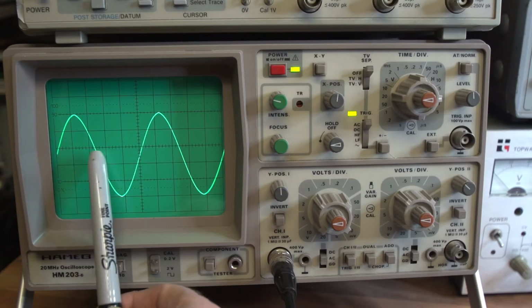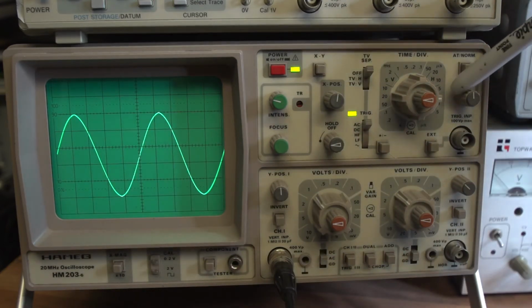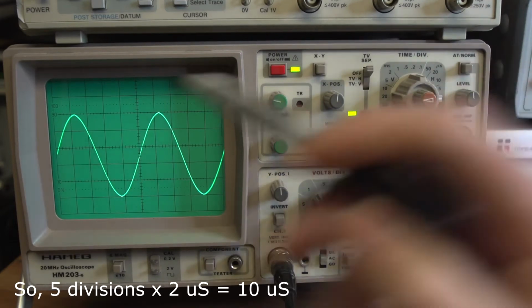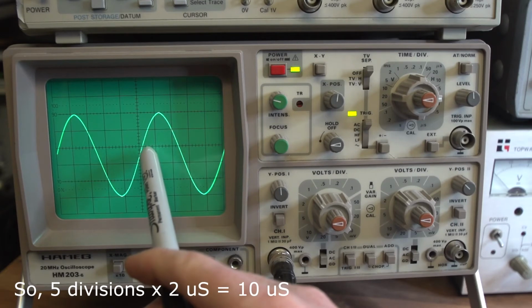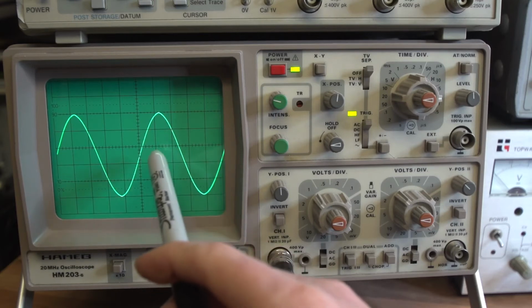It's 1, 2, 3, 4, 5. So that's 5 multiplied by the 2 microseconds, which means you don't really need a calculator for that one. That's 10 microseconds. 2 times 5. So 10 microseconds of time it's taking to go from the beginning to the end of a single repeating waveform. This would be another 10 microseconds, but we're not interested in that for the time measurement.